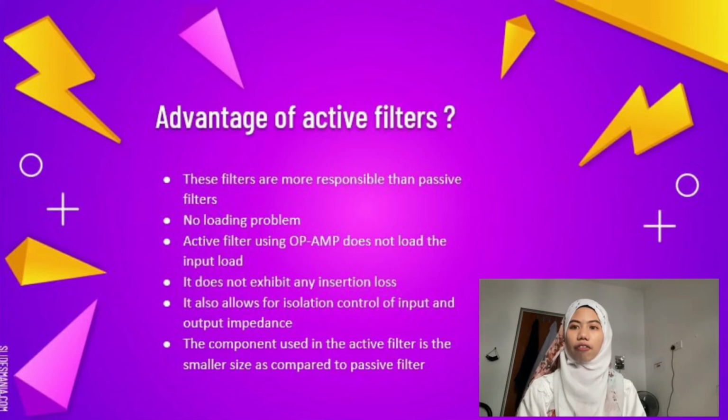For the advantages of active filters, there are 6. First, these filters are more responsive than passive filters. No loading problem: an active filter using an op-amp does not load the input. It does not exhibit any insertion loss. It also allows isolation control of input and output impedance, and the last, the components used in the active filter are smaller in size compared to passive filters.